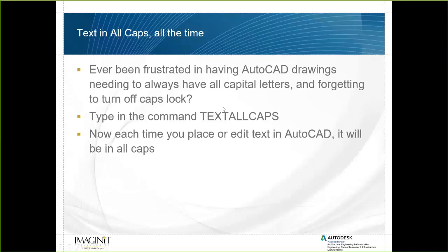So text all caps. Ever been frustrated in having AutoCAD drawings always need to have all capital letters and forgetting to turn caps lock off? How many of you have yelled at people over email, Skype, because you have your caps lock on, right? We've all done that. So now you can type in the command text all caps, and what that will do is that anytime you place or edit text in AutoCAD, it will be in all caps.